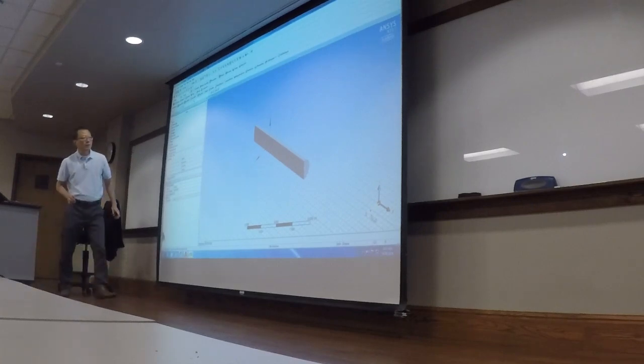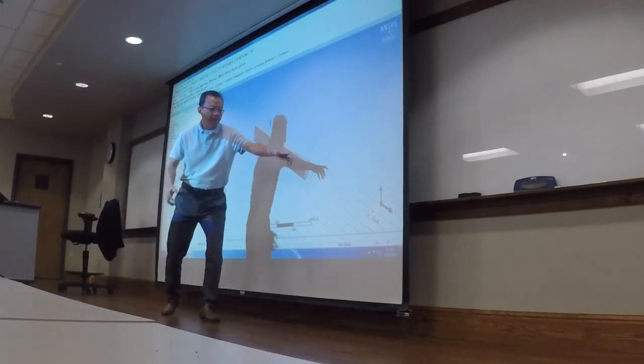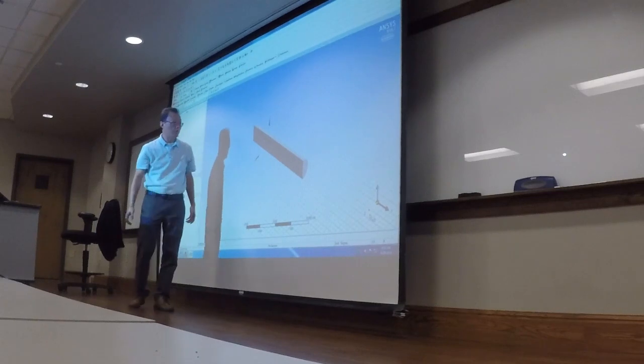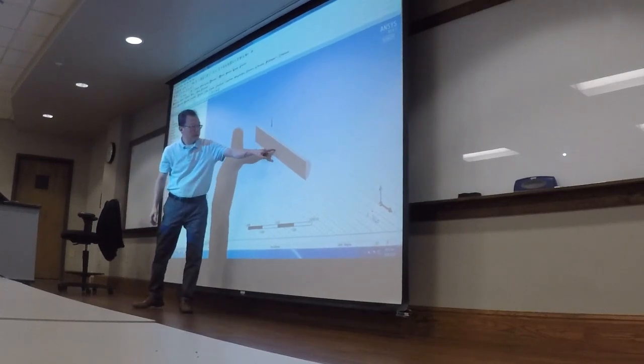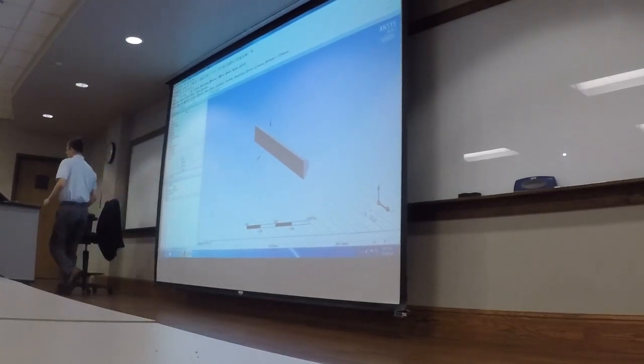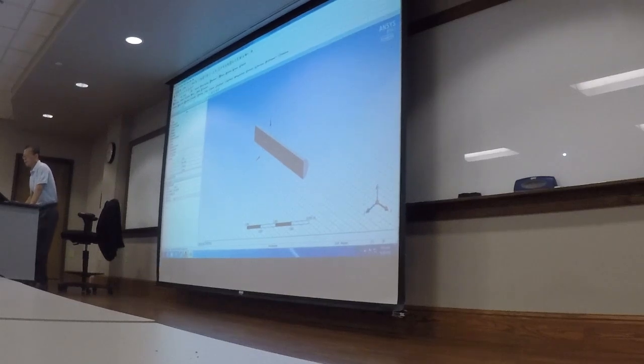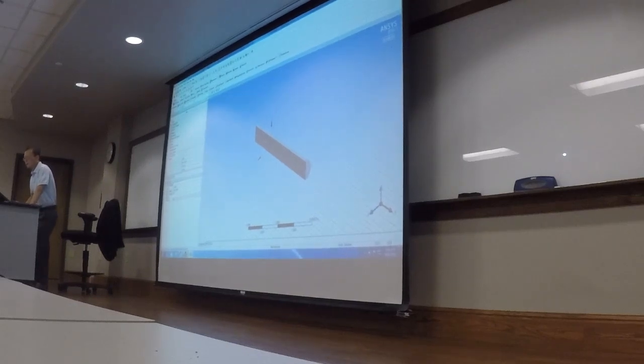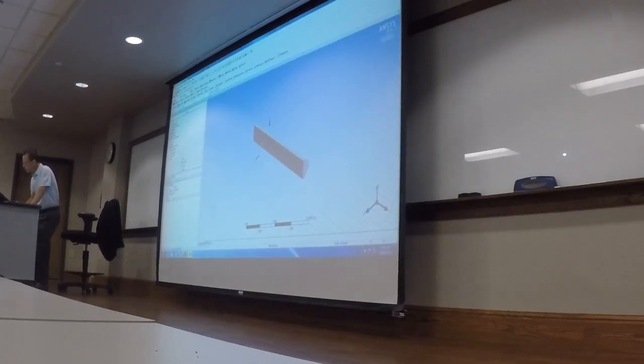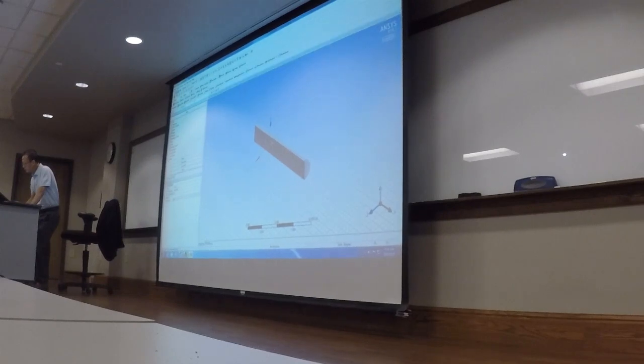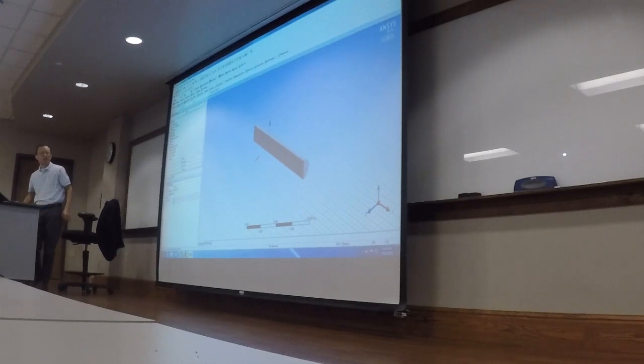So, if we click on the y-axis, we're looking down from the y. And this is the semicircle. Now let's close that. So go back to line, click, and close this diameter. All right. This is our sketch 2.